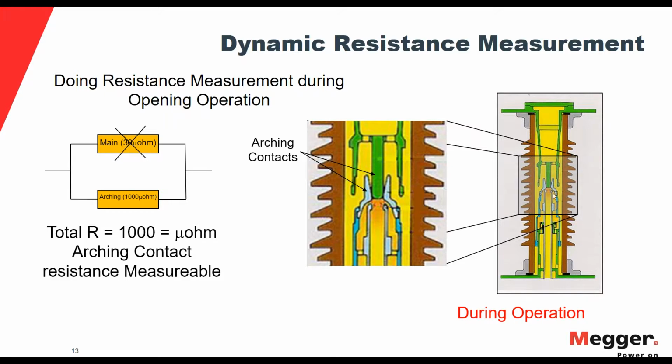As the picture shown here, I have only my two arcing contacts touching each other. Thus, the true measurement of my arcing contacts can be done in this operation.